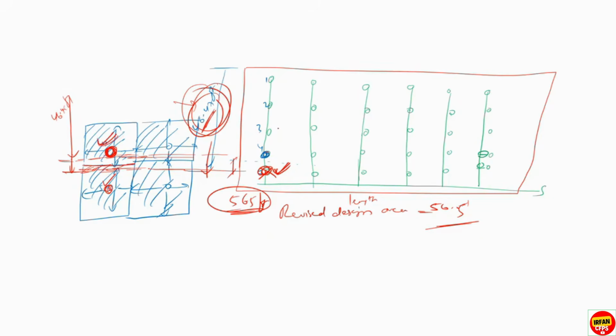So assume that our design area line is coming into the area of the fifth sprinkler, then we'll consider the fifth sprinkler. So the final length will be, we need to add from the wall how much, from this distance how much, from this distance how much, from here to here how much. Okay. And from here you need to consider half also, right?